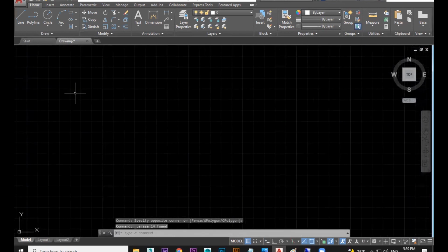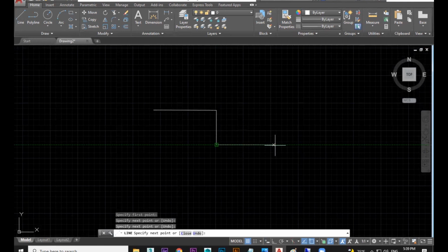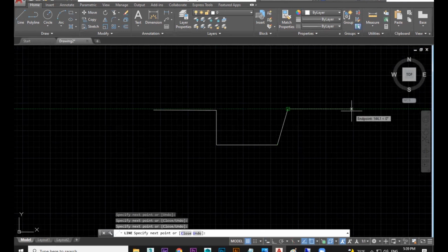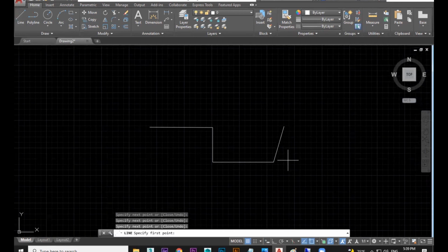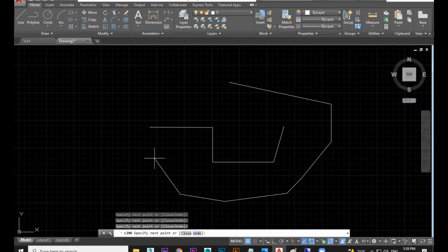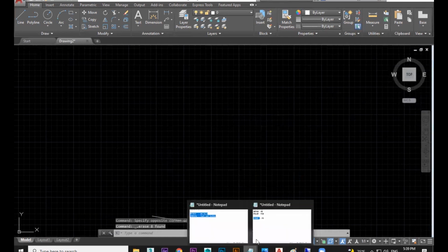Hope till now is okay. And remember one thing, if I draw a line with the line tool and want to end it, hit the enter key. Or if I want to stop it, instead of enter, escape can be used, enter can be used, or space can be used, any one button. It will end that. So I hope these three options are okay.